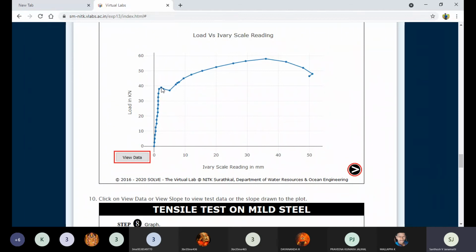There is no deformation percentage, only the one line, the elastic deformation line. Such brittle materials will not undergo plastic deformation. They will withstand only up to the yield point. Once we reach the yield point in that material, the workpiece is completely broken. There is no deformation. That happens only in brittle materials, but ductile materials are not like that.